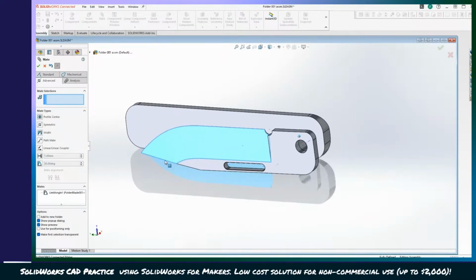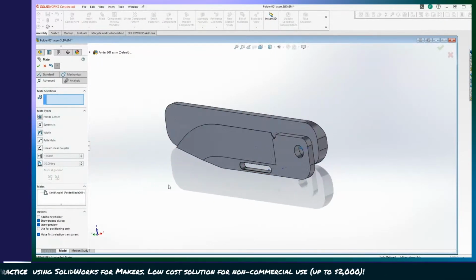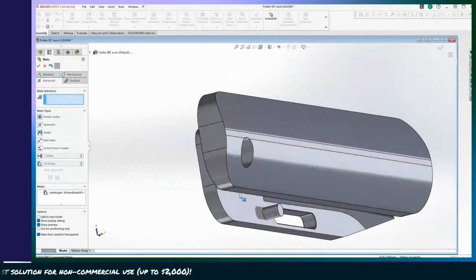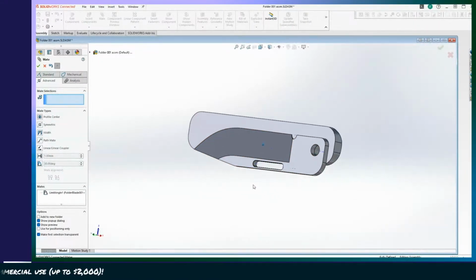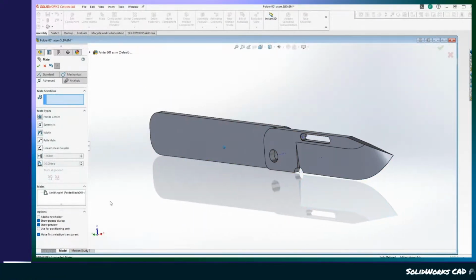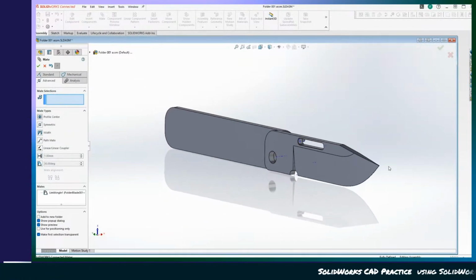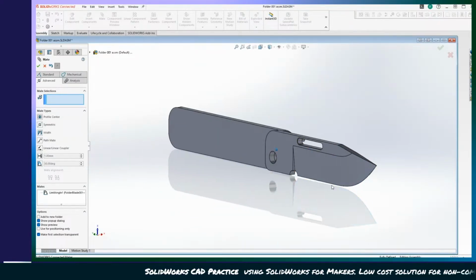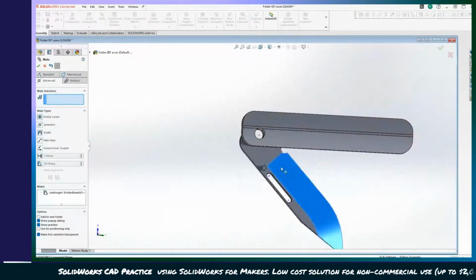We could change it to a little bit over 180 so that we could tuck that in, but we're not done here, so we'll probably move the pivot and so forth. But now we have that limit angle mate so that we can study what it'll look like during opening and closing.